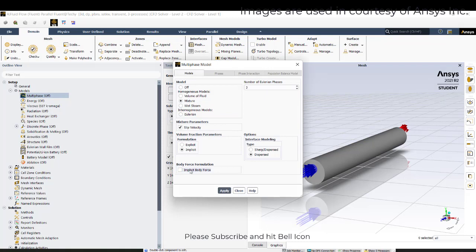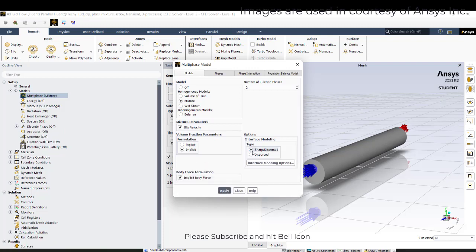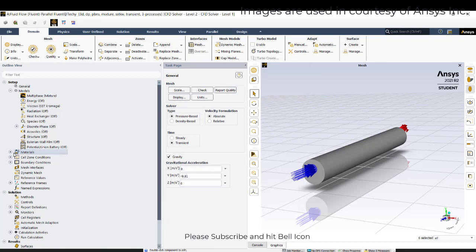With implicit body force activated, it stabilizes the equation. That's the reason why we activate implicit body forces. Now we can have a sharp or dispersed interface option. With these settings we can have a good interface between water and air. Click apply, and now we need to import water into our materials tab.